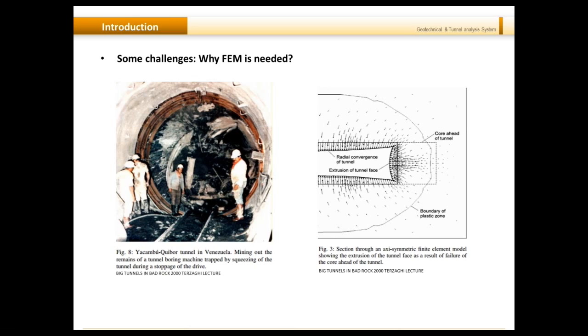There are given values that you can use to predict or assume this squeezing in the work area or behind the work area zone, but there's no standard computation formula available to assess the face pressure, because this is the pressure that is exerted onto the face of the tunnel boring machine.